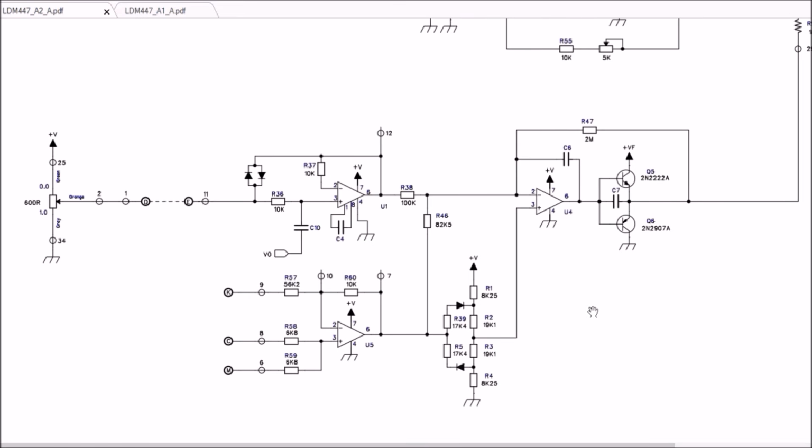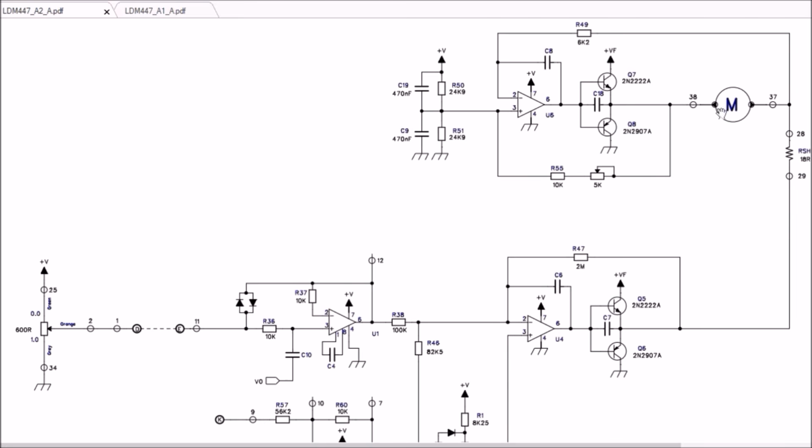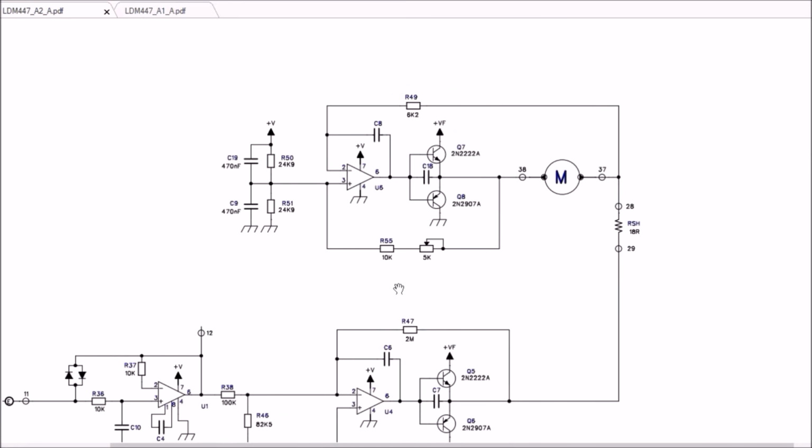We can see here the main circuit of this indicator. This is the servo control loop. The servo amplifier is here. There is a summing point. The DC motor is here. So this circuit is actually a virtual ground. This node is at mid power supply. So this circuit also simulates a negative resistance, which permits to compensate the resistance of the motor. So this permits a control of the velocity. We will see this circuit in detail later.